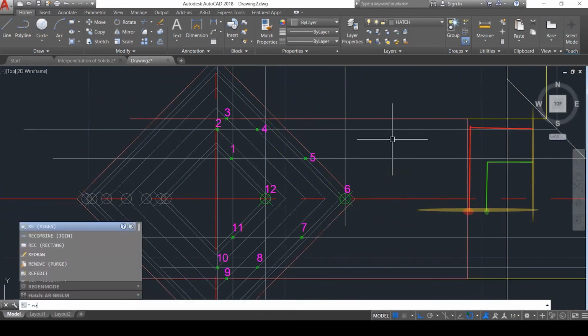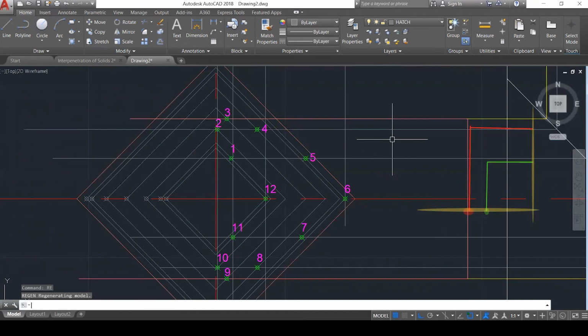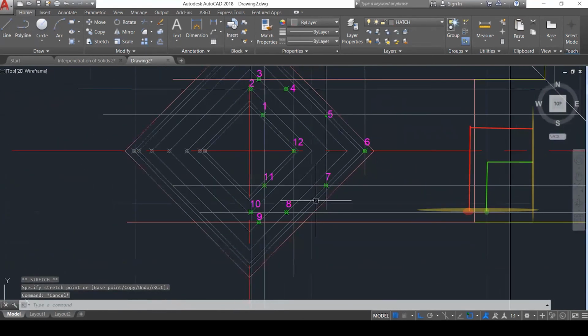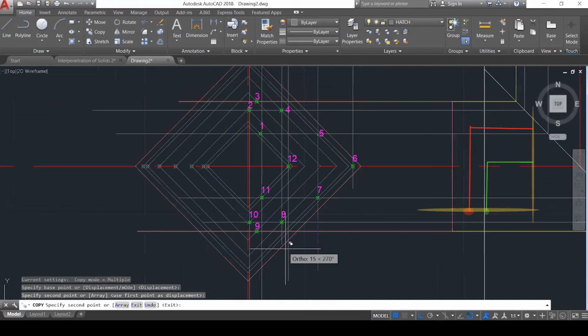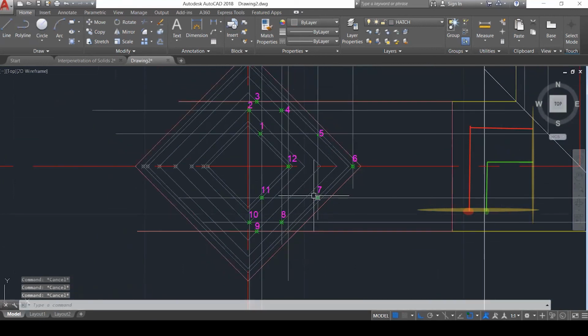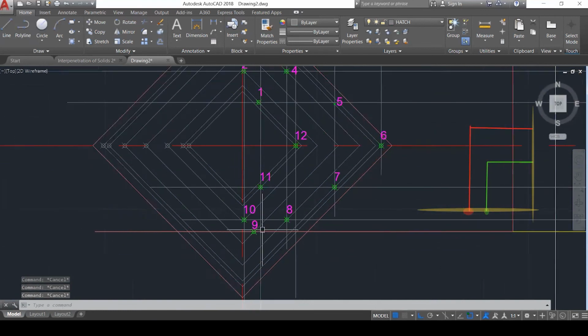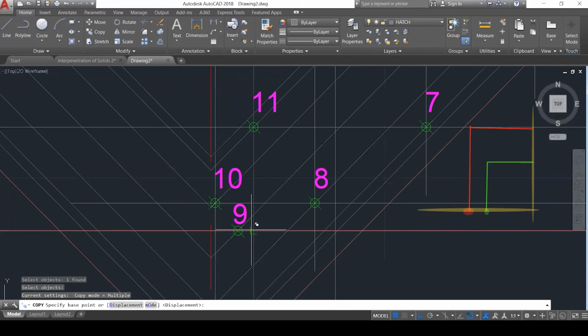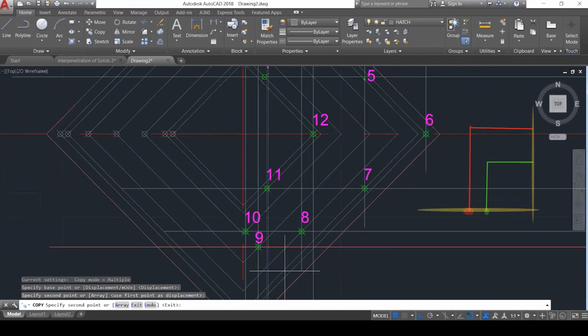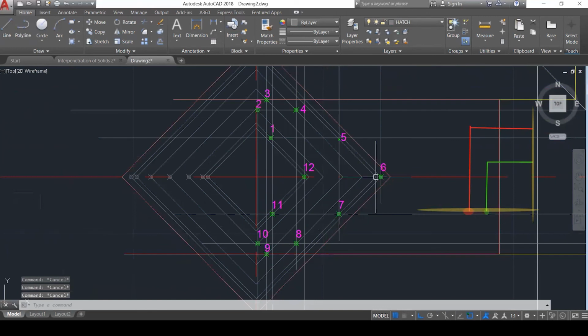Right, so let's refresh this. So that's the shape right there. But before I do that, let me transfer these lines up. Now let's transfer. I need to get a line for 8 and 4. Yep, 8 and 4, they're lining up. 11 and 1 line up. 9 and 3. I need a line for 9 and 3. So everything has gone up now. So let's create a spline.